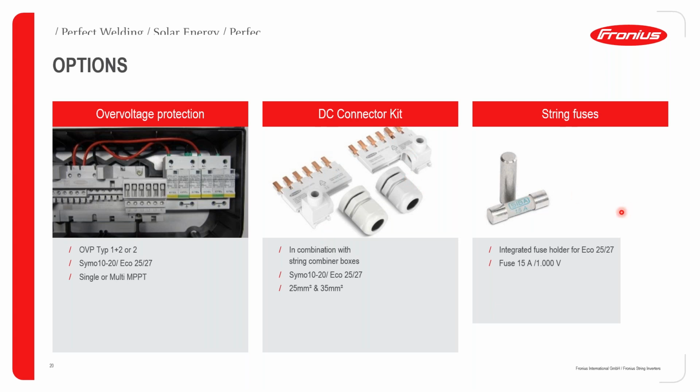Okay, moving on. Our inverters can also be ordered with string fuses. Only the Eco can be ordered with string fuses, so not the SIMO. If you are buying the Eco, you can order it with 15 amp string fuses, and this is internally integrated in the inverter itself.